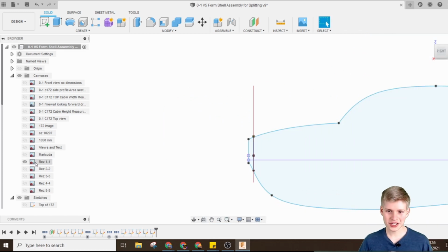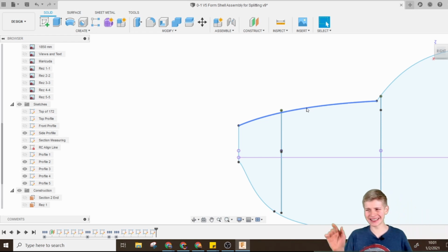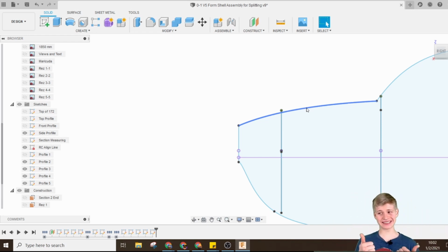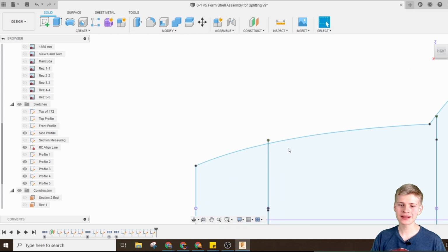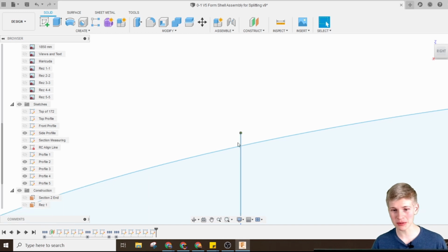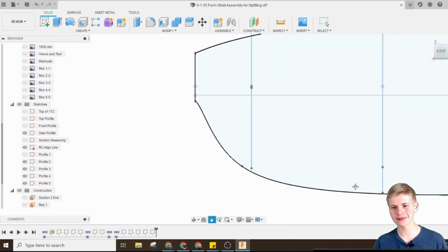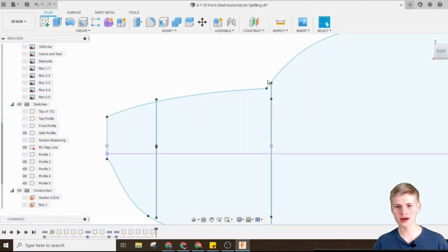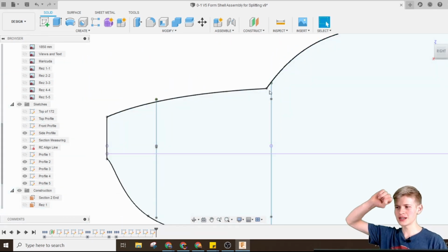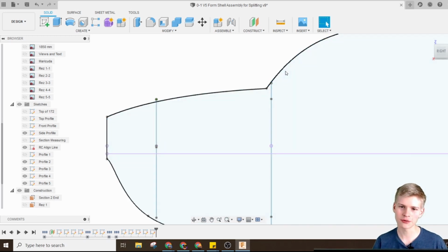We're gonna go to the sketches and make sure that they are constrained. I made a little mistake. Basically, I made these profiles completely disregarding where the top actually should be. So what I'm gonna go and do is go back and basically shift some of these up, and just take the endpoint and stick it to this side right here.